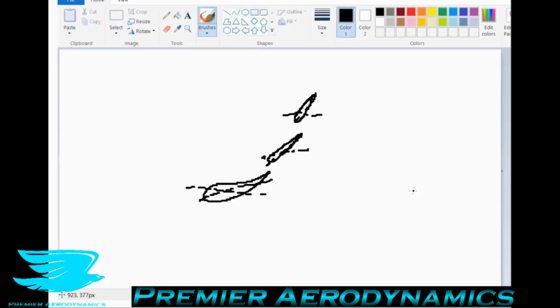The reason why is because when you have a low Reynolds number, it literally means that the flow does not have very much energy. Let's say we have a regular wing. Let's put it upside down, so we're going to be producing downforce. I'll get this one right. So we have a free stream flow coming in, and we have a boundary layer forming over the suction side, sorry. The flow near the wall is going to be quite slow.